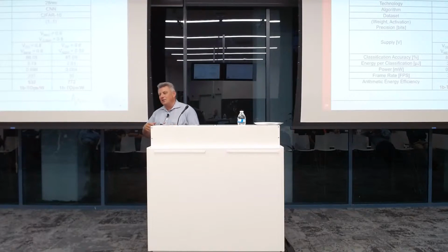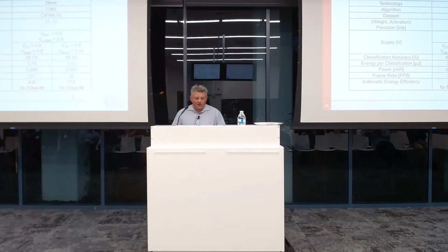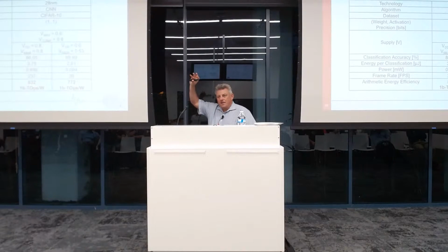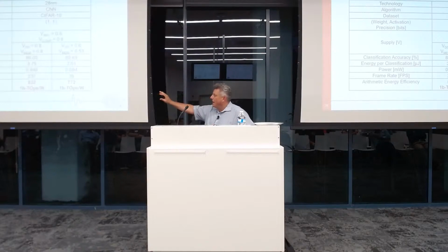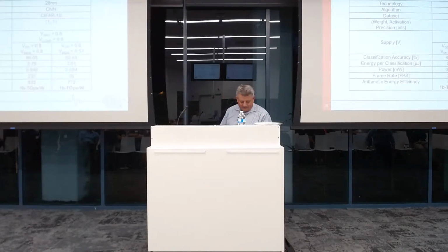It's much easier than a 4-bit or an 8-bit multiply add. But nonetheless, this is not a horrible number. Remember my NAND gate example in the beginning, that was 5,000 TOPS per watt. You can see we're about 10x below the NAND gate limit, which means there is not much inefficiency here. There is not a whole lot you can cut out, unless you make a very dramatic change in the architecture. And that's what I'm going to talk about toward the end.